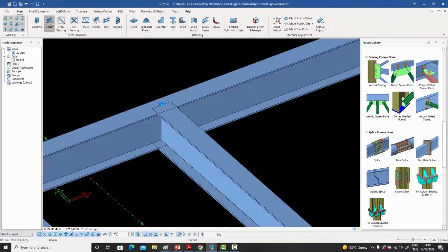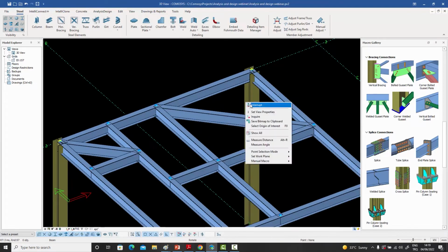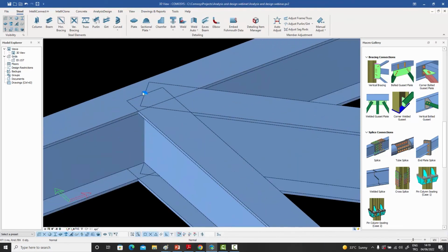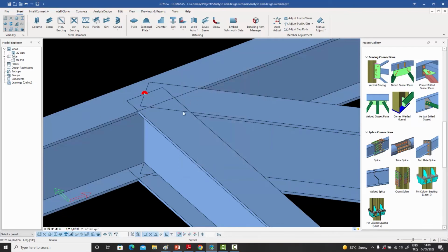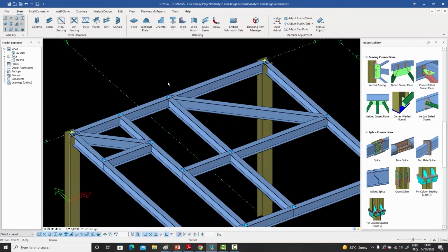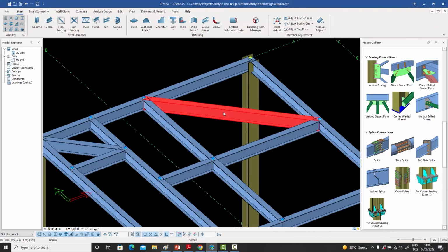So if I had another beam, for example, from here to here, now if I double clicked on that, the connectivity would be 3, but still this one would be the continuous one, and the other two would have to be end points. So if one of the elements is continuous, the node will turn blue. But if all are ending or starting at that point, then the node will be yellow. Now, what you're not allowed to do is something like this.